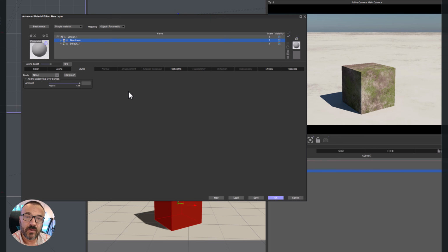For us to understand bumps or highlights, bumps up or down, holes, we can only recognize them by shadows and highlights. And that's what happens here. The engine analyzes lights and the effect of the bumps and creates a simulation of the bumps. A bump map does not change the shape of the surface or object at all. It just gives these representations of shadows and highlights to simulate them.